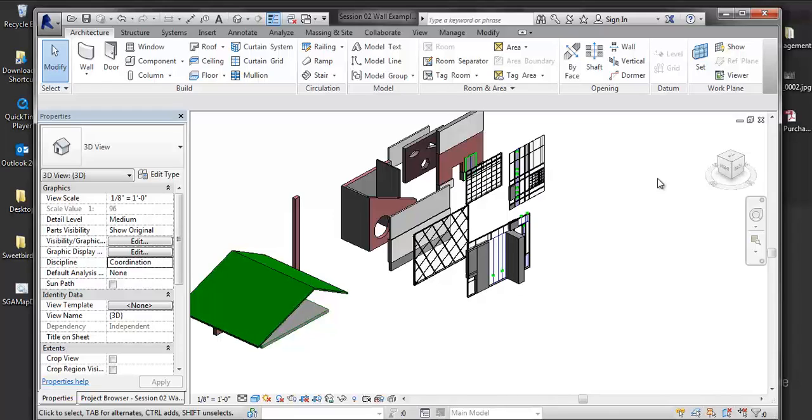I like to keep things minimal. I like to minimize the amount that I constrain within that model. So I typically constrain really, really important things: grids and levels, certainly, and controlling geometry, the exterior walls relative to easements and property lines and things like that. Then I'll lock those down. Most everything else, I want to be able to flex and move.